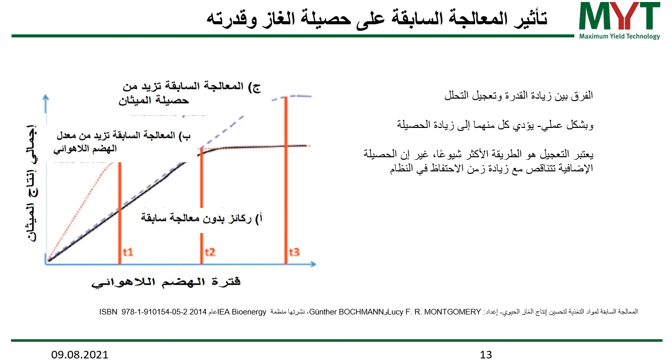And this is shown here in this graph. You can see this red dotted line is an accelerated degradation process, and you end up at the same potential, but in your process, which is T1, this red line here, you can see that you would achieve at this point of operation a higher yield. But it tells us also that if you have a very long retention time, as you can see in T2, then your acceleration of your degradation process has not a large impact on your gas yield.